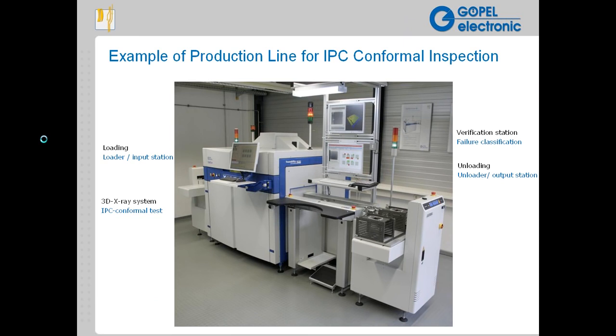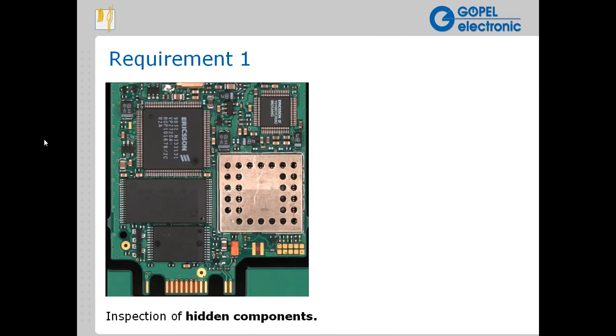As you can see in the X-ray image on the right, we can in fact see the device underneath the shroud. If you look closely at the pin images of that particular device, you can see the varying grayscales for the hill of the solder meniscus. So even through a metal shroud like this, we can often get visibility. This can be different if it's a very large, thick heat sink or some kind of material like that on top of the device. You can't always see through impeding structures, but in many cases you can.